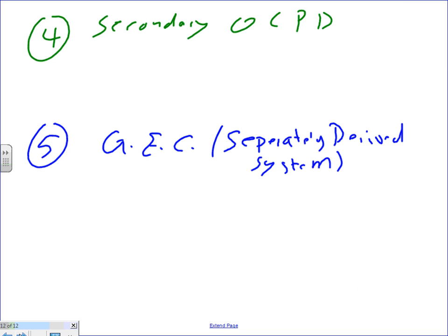Okay, let's do number 4. Secondary overcurrent protection device. It doesn't matter actually if it's a fuse or circuit breaker, really doesn't matter in this calculation for the secondary. So the multiplier in either case is going to be 1.25 multiplied by the full load amp that we came up with, 1806. That will get me a healthy 2258.